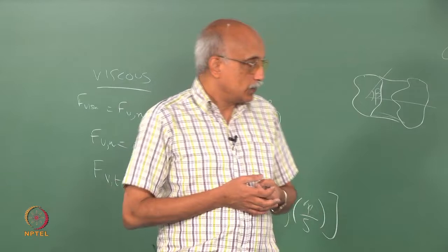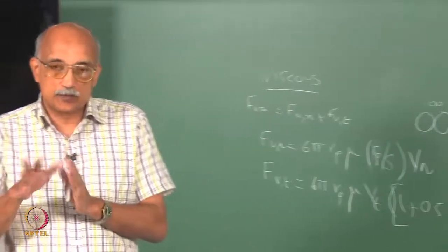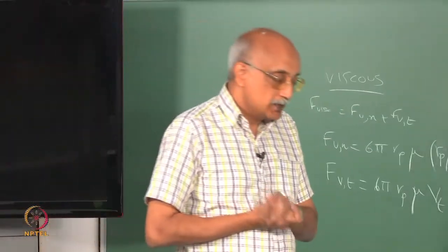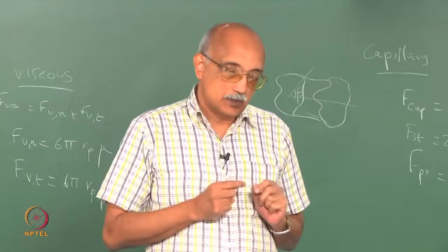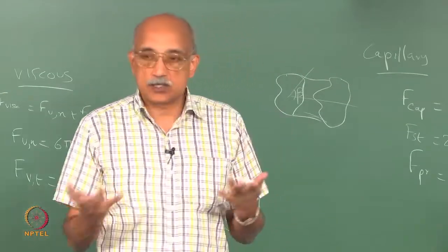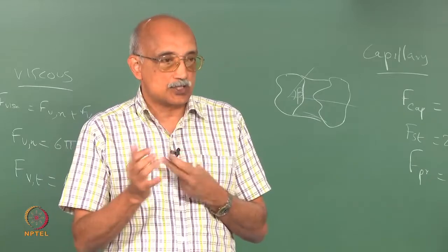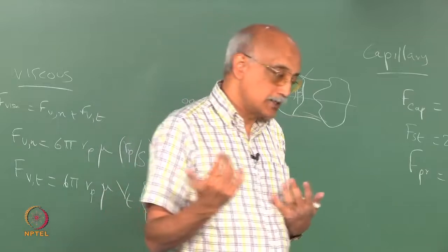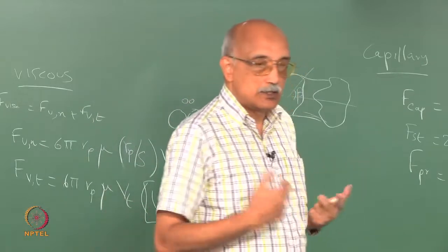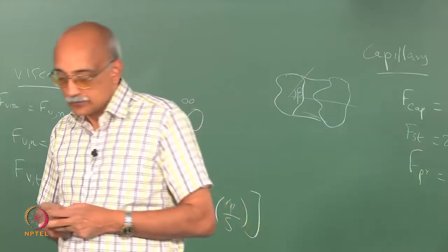So, the tangential force is only effective as long as the particles are reasonably close together, which means that this tangential force becomes increasingly important in concentrated solutions, because as the concentration increases, the distance of separation between any two particles decreases. So, the tendency for the tangential spring like force to keep the particles together increases.